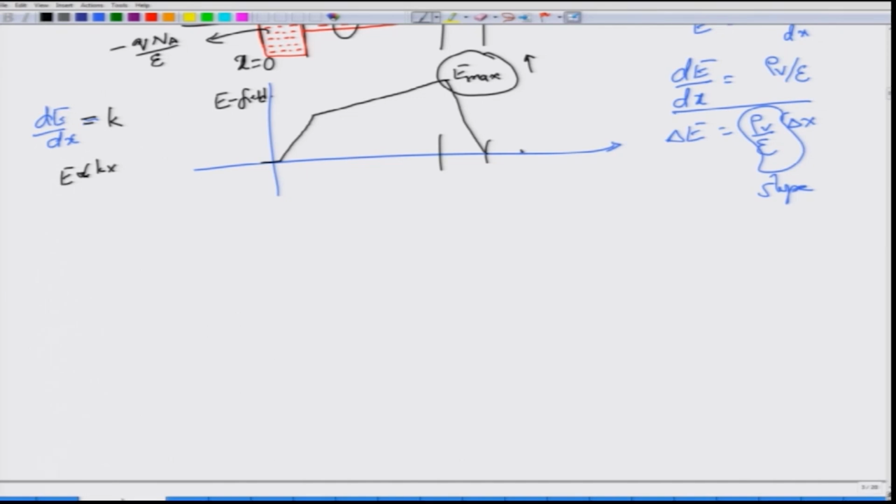Okay. Now, this is for the electric field, all these terms, but what you are probably interested in, if you are designing a photodiode circuit, is what would be the current and the voltage characteristic, right. What would be the current and the voltage characteristic. So, if you go back to a simple PN junction diode, you already know what the current and voltage characteristic will be, right. So, you start typically with some very small dark current, very small negative current, and then the current will be 0, and then it will start slowly to rise, and then eventually it will rise off, right.